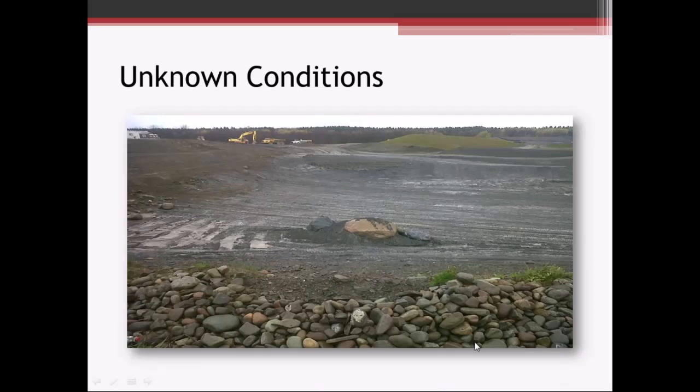I like to show this in my geotechnical presentations just to emphasize the variability of subsurface conditions. It's really by chance that you may or may not find a condition like this. The best we can do is investigate enough locations across the site to get a generalization of subsurface conditions. We just don't want to take one sample at one location for most projects.